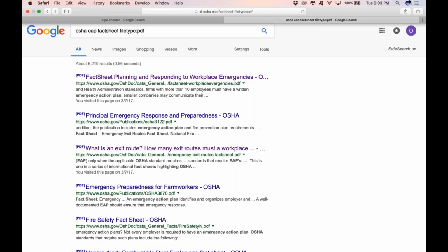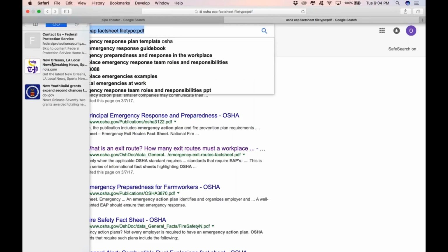Okay. During demolition and alterations, existing automatic sprinkler installations have to be retained in service as long as reasonable, right? But if not, we still have to have fire extinguishers available, right? And we always have to have those fire extinguishers available if we don't have some type of standpipe or fire sprinkler systems available. Okay, and all structures in which standpipes are required, and I'm going to show you the standpipe. Let me show you now, folks, for anybody, because I want to make sure that everyone knows what I'm talking about.